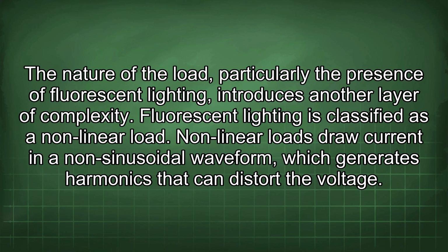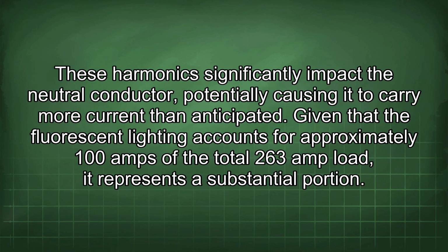The nature of the load, particularly the presence of fluorescent lighting, introduces another layer of complexity. Fluorescent lighting is classified as a nonlinear load. Nonlinear loads draw current in a non-sinusoidal waveform, which generates harmonics that can distort the voltage. These harmonics significantly impact the neutral conductor, potentially causing it to carry more current than anticipated.